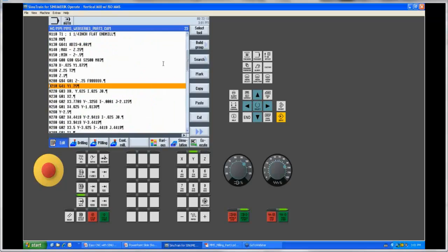okay. When you use the FANUC compatible mode for turning, is there any way to select what protocol of G code the system is reading? Yes. When it comes to FANUC, they have 3 different protocols they followed over the years, kind of as they grew with the control. They had FANUC A, then they went to FANUC B, and now they're at FANUC C. You don't have that issue in MIL, so I didn't have to show it, but we do have a back-end parameter that you would set up, so however your programs are coming in, A, B, or C, you would just make sure that that back-end parameter is set to it, and then we'll read that.